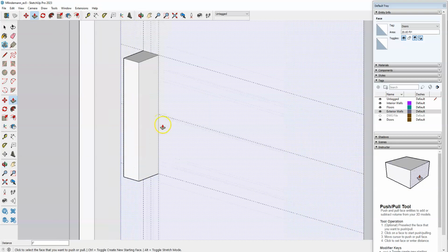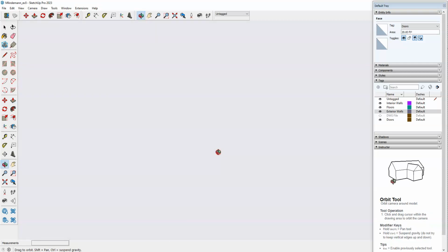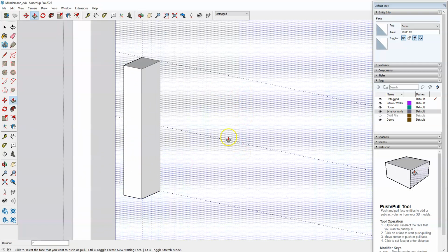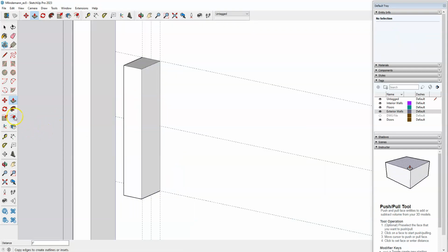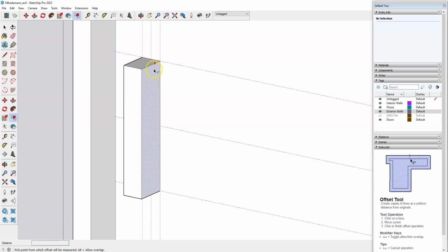And then if you want to make it a little bit fancy from here, because obviously this is probably not what a door handle is actually going to look like, you can create a little opening in here. So I might use the same offset tool, maybe I'll bring it in 1 inch.